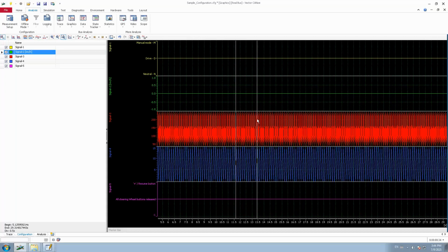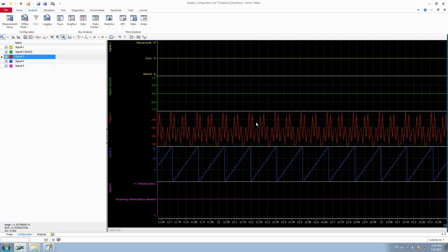Now I'm going to see the signal transitions in detail, in a zoomed manner, between these two cursors in the x direction. That's how you could zoom in on a particular section of your signals. When you select the scaling as X, you will find a two cursor option in the horizontal manner.